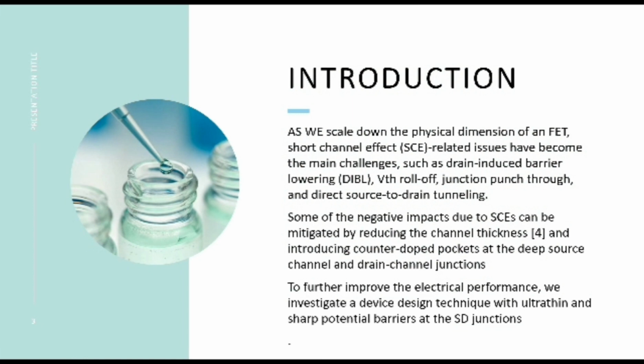First of all, if we see the physical dimensions of a FET, the short channel effect related issues have become the main challenges, which include drain-induced barrier lowering, VTH roll-off, junction punch-through, and direct source-to-drain tunneling. And for reducing the negative effects of short channel effect, we can minimize the channel thickness and introduce counter-doped pockets at the deep source channel and drain channel.